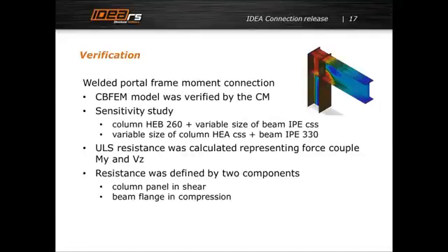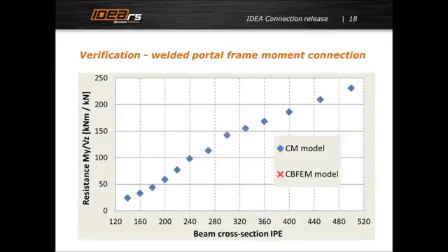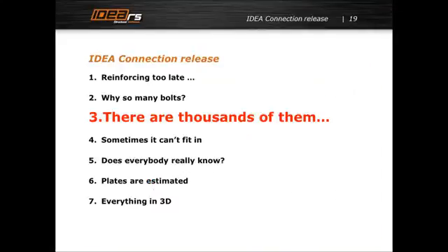We do verification studies like this knee connection. You can see the results calculated by the component model and the results calculated by the SBFM model. The agreement is less than 5%. The same we have for bolted connections and base plates.